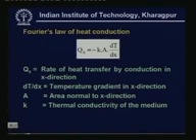That means we should know the temperature as a function of spatial coordinates. Then you can find out the heat transfer rate by conduction, provided you know the thermal conductivity and also the heat transfer area. And the negative sign in this equation is a consequence of second law of thermodynamics.